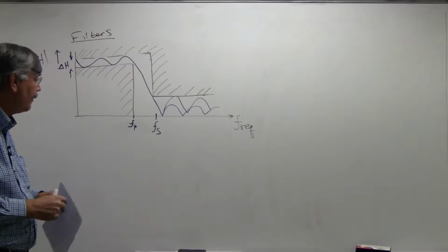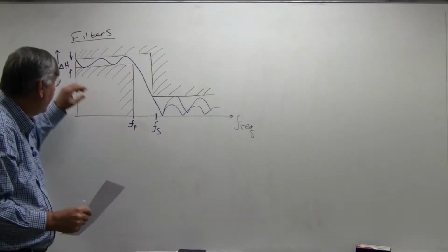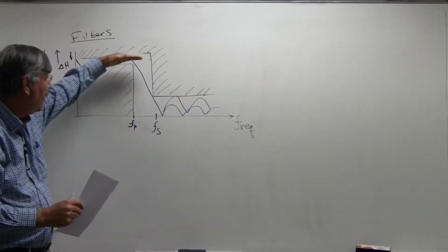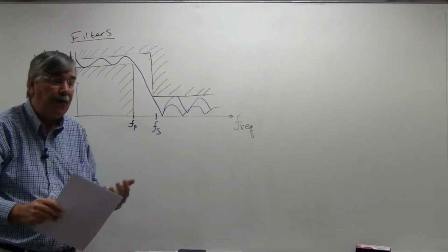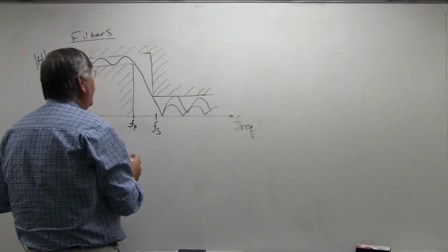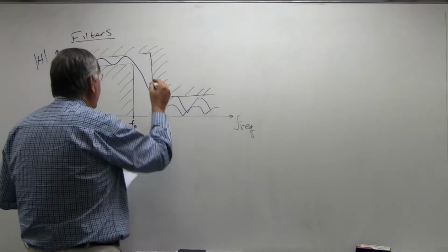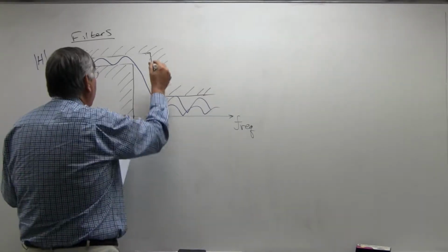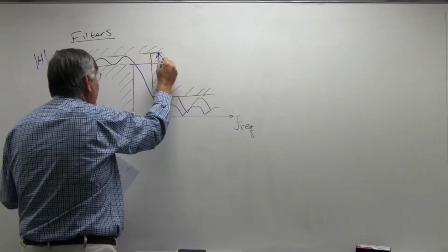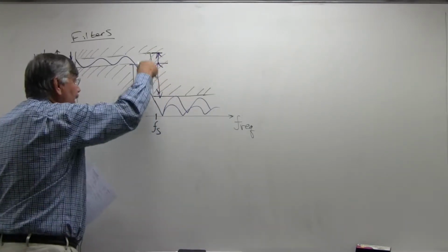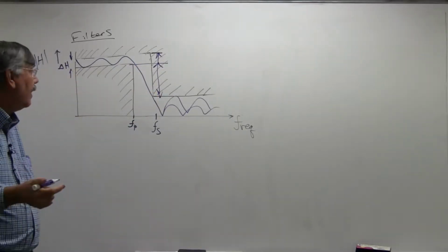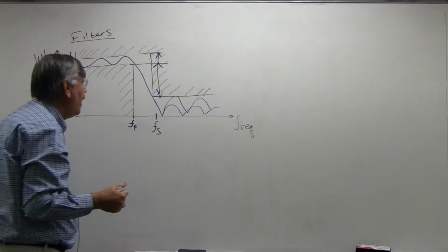Okay, so the amount of attenuation and the locations and the amount of variation in the pass band, the amount of variation in the stop band, the amount of attenuation, those things are the main specifications of the filter. And one that's very important is the selectivity. If we talk about the total amount of attenuation that we're guaranteed to have, at least this much attenuation between the pass band and the stop band, the more of that, that adds to our challenge.